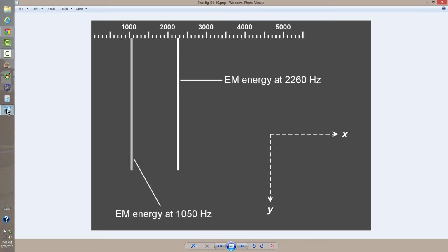There's a program called Digipan, D-I-G-I-P-A-N, and you can download it and use it as an audio spectrum analyzer that goes from roughly DC to about 5,500 hertz in the audio spectrum. By installing it in your computer and then plugging an antenna of sorts into the microphone jack, you can monitor the electromagnetic fields, EM energy, set up by the alternating current that goes through the wiring in your house.